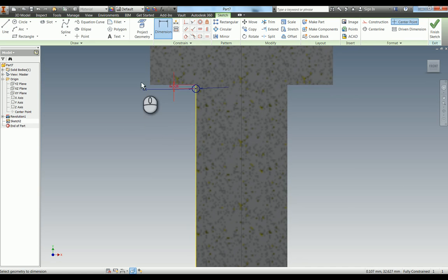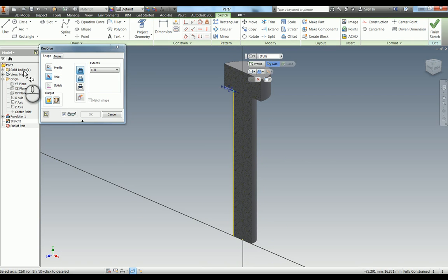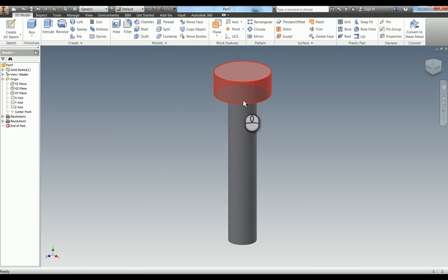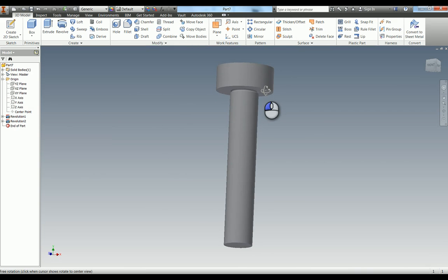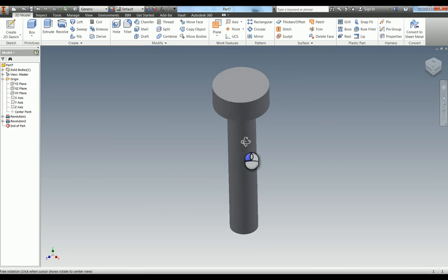And now I'm going to use the revolve button. It's picked up the profile, of course, but didn't know what the axis was, so I'm actually just going to use the y-axis in there, and it's already defaulted to cut because it knows we're trying to cut the material away. So I'm just going to hit OK. That's our undercut done. I'm now going to put the aluminium key hole in the top, so S for sketch,